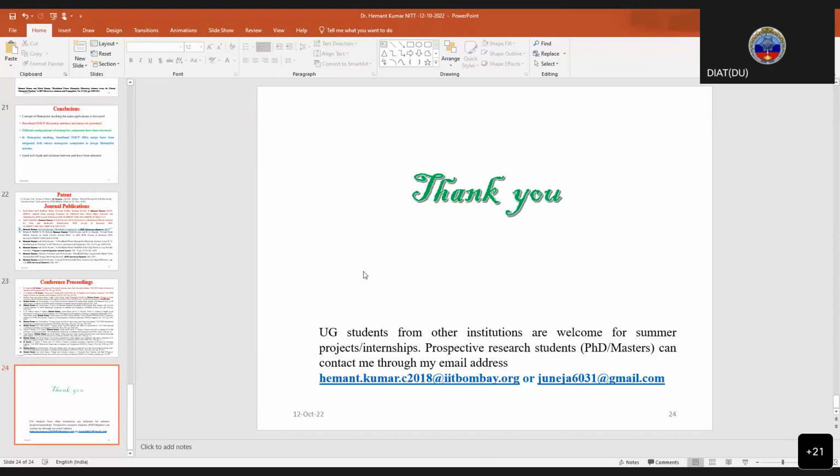Sir, I am designing the antenna for the millimeter wave frequency range. So what exactly is the frequency range? Around 60 gigahertz, or maybe less? It is between 24 to 40 gigahertz. 24 to 40. Okay, so it is not a small band. It is actually a wide band. So you can choose this monopole kind of antenna. Otherwise, if you use a patch antenna, then you have to do more with that to get that much bandwidth.